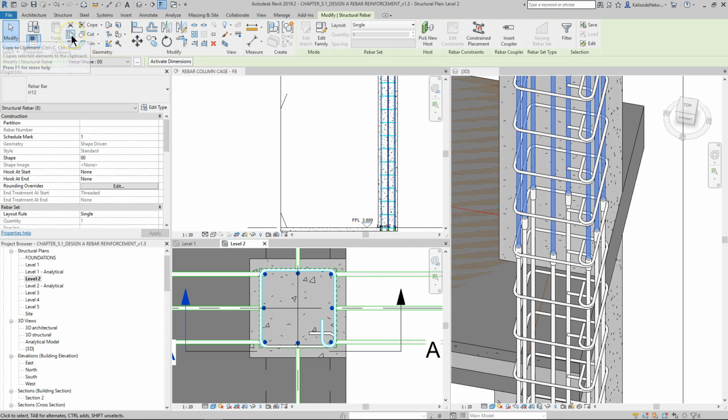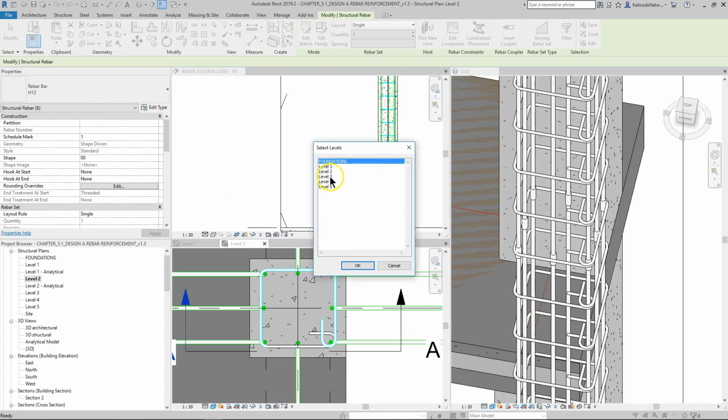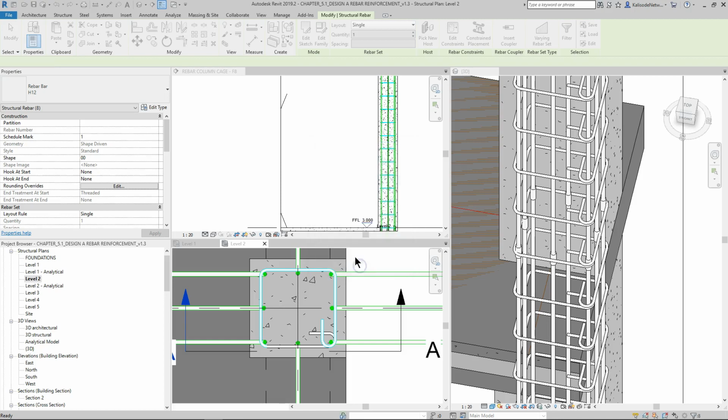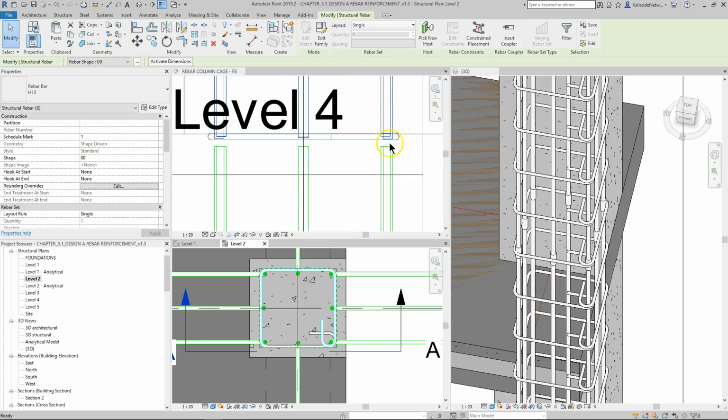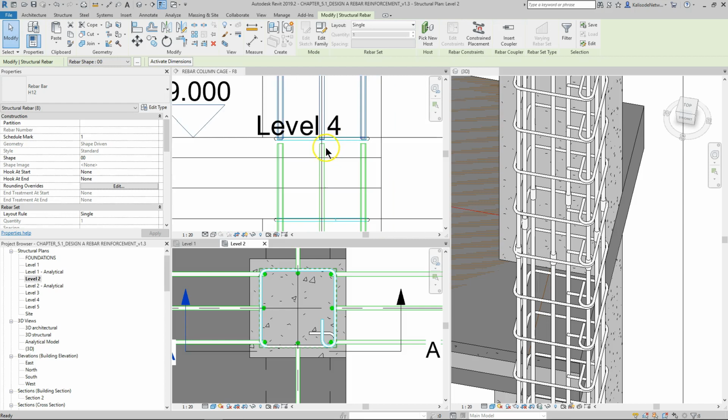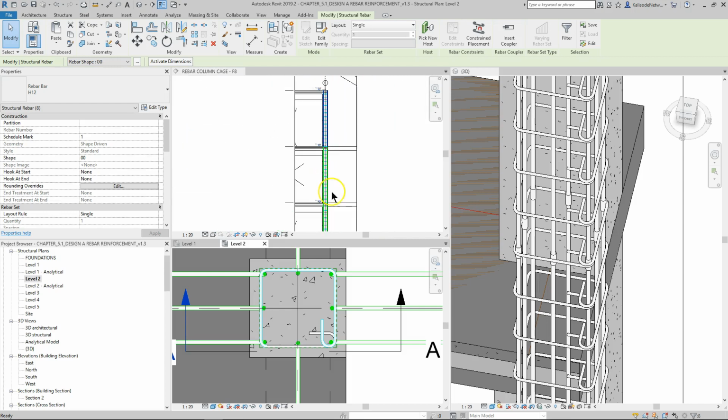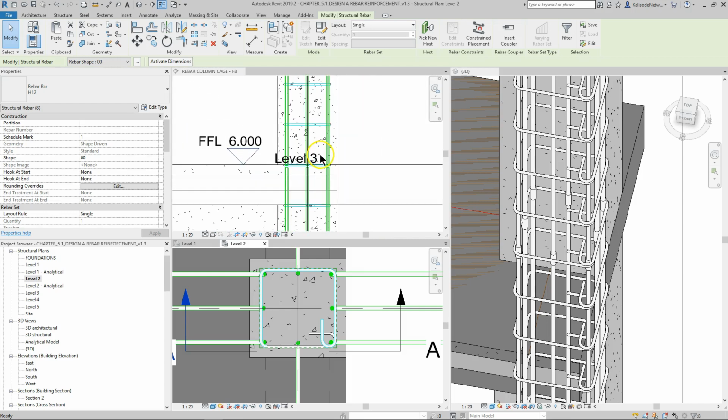I would simply make a copy to clipboard, and then this is very powerful: Paste Aligned to Selected Levels. You will use it in a bunch of cases here in Revit, and it's a very fast command. It will just copy and, exactly in the same place, align to the following 2 levels. Click OK, and my job is done, with a little space for the rebar couplers that I will do in a second moment, and the whole column is now ready.